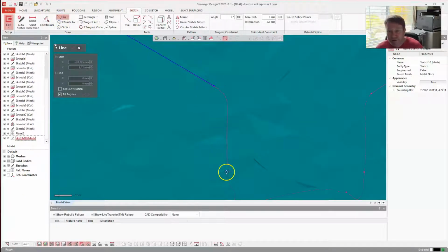It'll make more sense once I show you what I'm doing. I am going to try to make a vertical line right here. And then, with tools similar to SolidWorks, I'm going to extend this one to there. So let's go here to extend. And then trim.